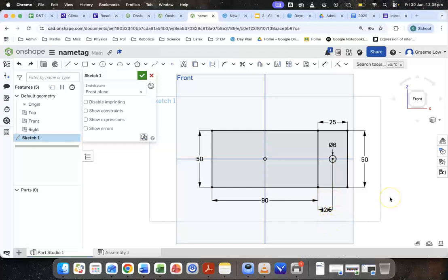So that's looking pretty good. I kind of want this to be rounded over here, I reckon. And I also want the corners here to be rounded as well. Makes it a nicer shape. Also, when you're 3D printing, unless you absolutely have to have sharp corners in your design, you tend to get better results if the corners of your shape are slightly rounded, because 3D printers don't like really hard 90-degree turns. They can look a bit messy sometimes, particularly if you're trying to print fast.